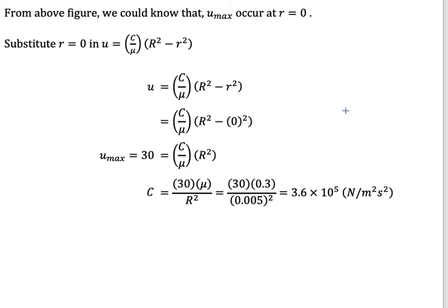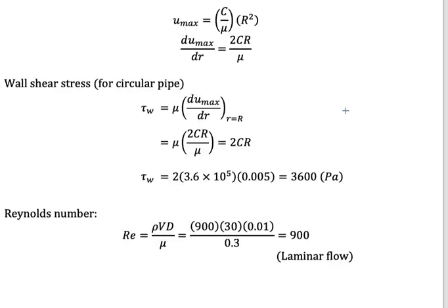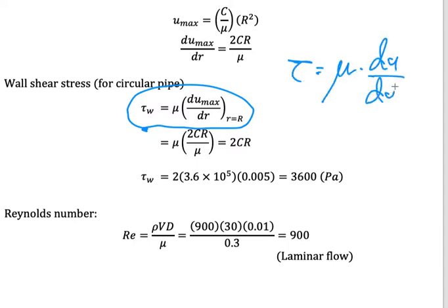So, okay, I'll just jump this one. This is the equation for wall shear stress. The common equation is tau equals mu du dy. However, in this situation we don't have the value of y. You could imagine that we have Cartesian coordinates and polar coordinates. In polar coordinates, we change y there to r, so it is mu du dr.